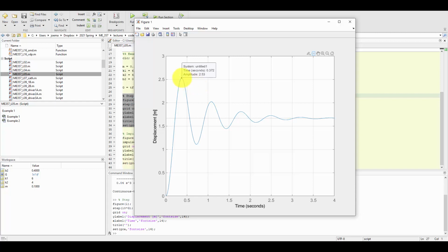And then it comes closer to the equilibrium point, 1.11. Then it goes less far away than the first time, and then that keeps happening. This is because we have that damper that is dissipating energy out of our system. And eventually it's going to come to the steady state that is below that initial equilibrium point, which was x equals 0. It's now at 1.67 meters, in that positive x direction, from the equilibrium point. So we have these oscillations around the new equilibrium point when we apply this step function.